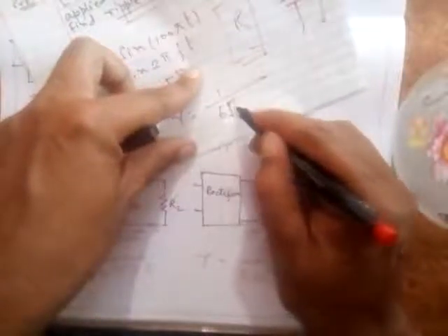I told you the formula yesterday for this LC filter, if you remember. It is given by 1 upon 6 root 2 omega square LC. 1 upon 6 root 2 omega square LC. Substitute the value of omega, which is 2 pi f, with f as 50. You can find the value of omega and find out all this. Do all these calculations here. Everything is given to you. You'll find that this ripple factor is equal to